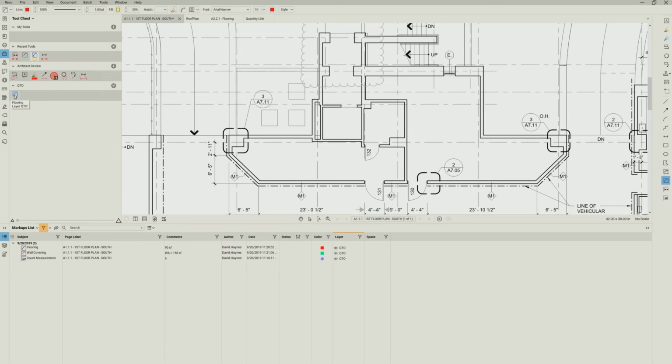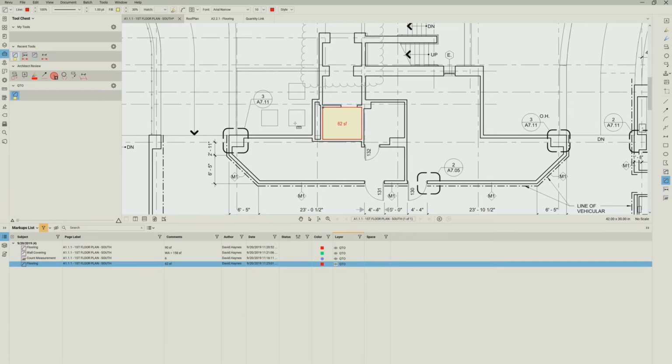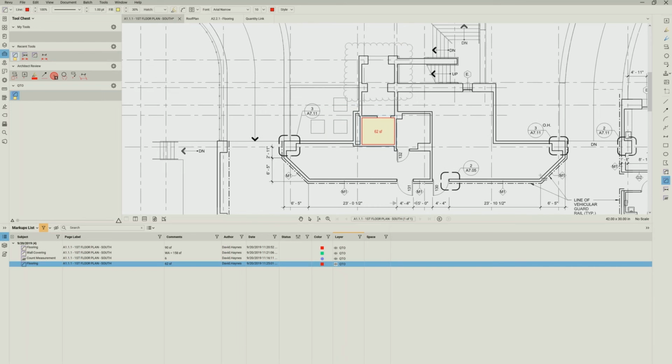And really what we discuss is the difference between property mode and drawing mode. I wanted it to be in properties mode, believe it or not. And so let's suppose this, I'm going to use something simple here again. Now I don't need to recreate everything. I click this, and now with my snap to content on, there we go. The only thing I'd have to do maybe is move that if I needed to. And you see it comes down here. Notice that comes in on the right layer, and so forth. So that works out really well. That's one way I could do it. And really a great way, if you set it up once and you really like it, you could just drag and drop.